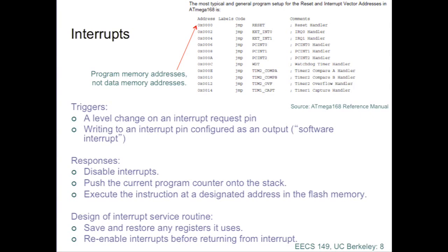And, sorry? The compiler doesn't create a new stack, right? It uses the same stack. In this architecture, there's only one stack pointer register. So if you want to put an operating system on an architecture like this, what is meant by a thread, in fact, is a sequence of execution with its own stack. But in most of the hardware, there's only one stack pointer register. So the operating system is reading and writing to the stack pointer register to create this illusion that you have multiple stacks. Okay, but anyway, the most common thing is to push the state of registers onto the stack.